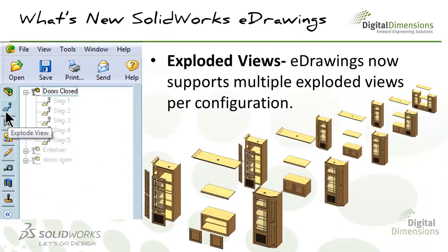And first up for SolidWorks eDrawings 2013 What's New is the support for multiple exploded views per configuration. One of the highlighted enhancements to SolidWorks 2013 is now the ability to generate multiple exploded views per configuration in both your multi-body part files and your assemblies.